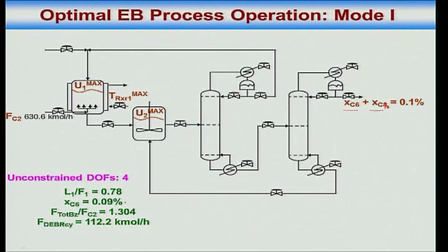These things need to be thought through. Why is the temperature of reactor 1 max active? The second reactor is adiabatic, so you will maximize the temperature in the second reactor, and therefore you will maximize the consumption, the transalkylation, the DEB consumption in the second reactor, and therefore DEB will not build up to that large an extent. Diethyl benzene will not build up to that large an extent. Does that make sense or no?